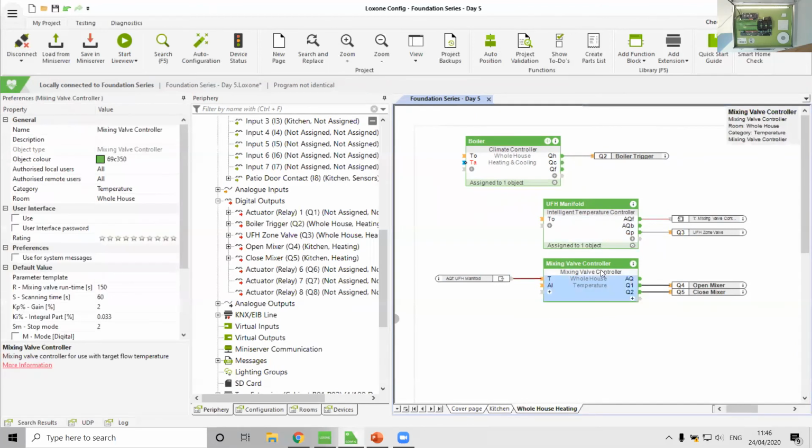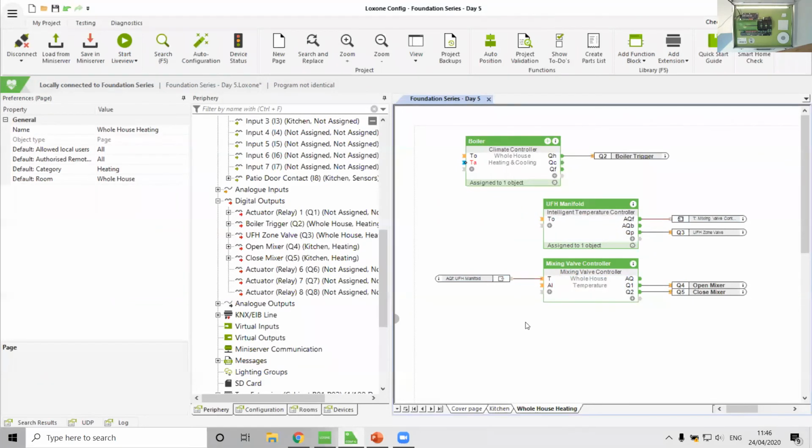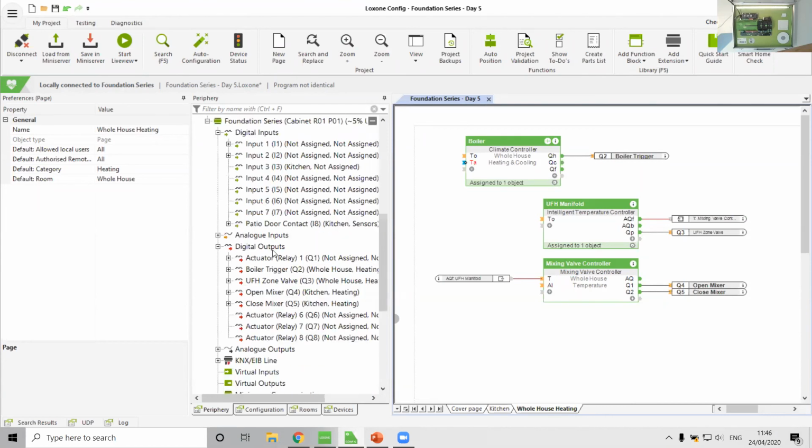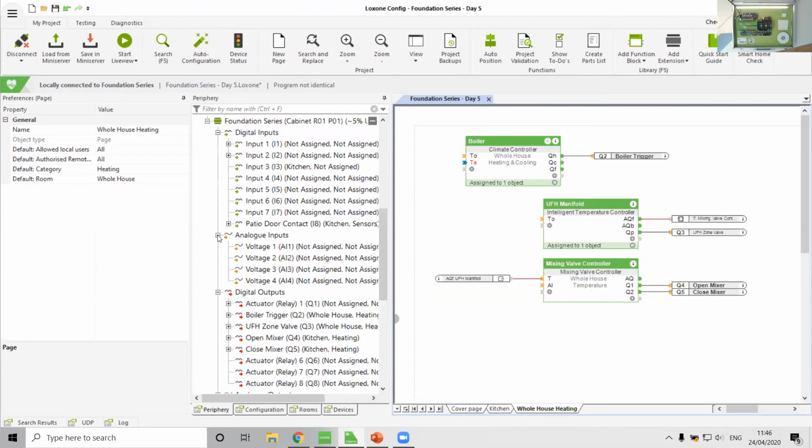The second thing this needs is the real flow temperature. To do that, you would strap a probe to the pipe or you would have a probe in a thermowell in your hot water or buffer tank. You would quite often do this through 1-wire. So we actually have a 1-wire extension and we do sell 1-wire probes as well. However, to show you this actually working,